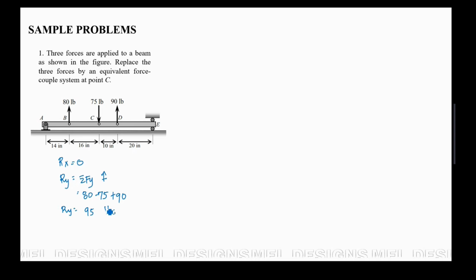Next is the moment. For our moment, what is being asked? The equivalent force couple system at point C. So our equivalent moment will be referred to point C. So the resultant moment will be referred at point C. Therefore, it is equal to the summation of moments at point C. So let's start with this force.